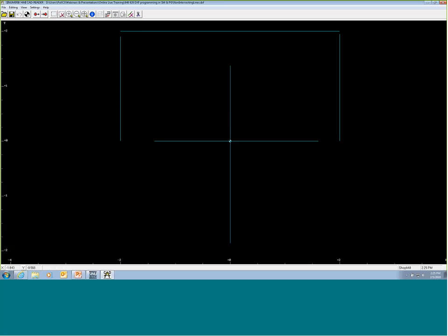Okay, now just talking about the layout, when you're looking at the CAD reader, there is a little display in the lower left corner. This is very handy. It allows you to track not only where the mouse is, but you can also figure out where the zero of a print had been created. In this case, I have a little bullseye, and if I hover my cursor right here in the center of the screen, I can see that that's 0, 0. As well, you have the hash marking to give you some perspective on scale.